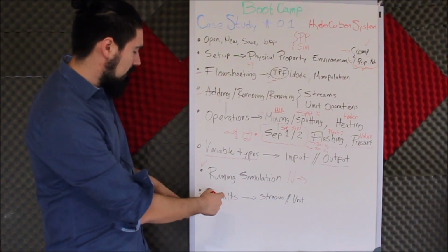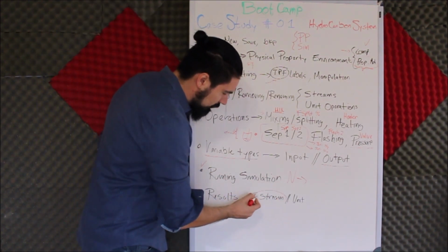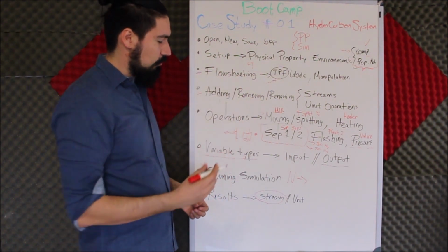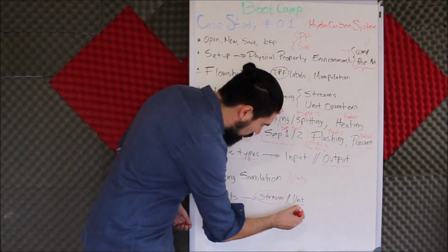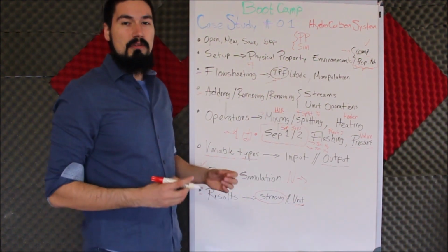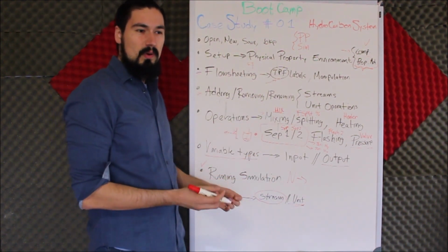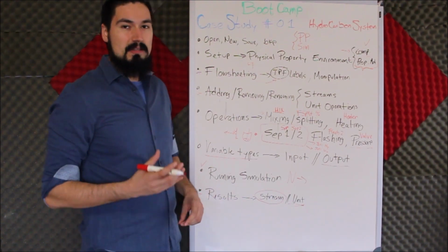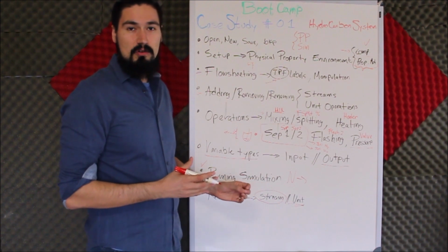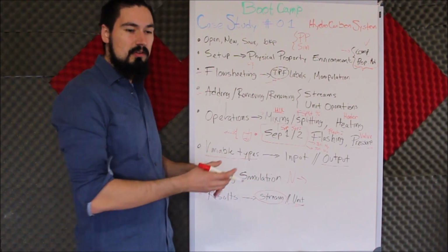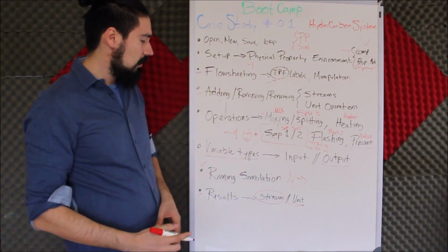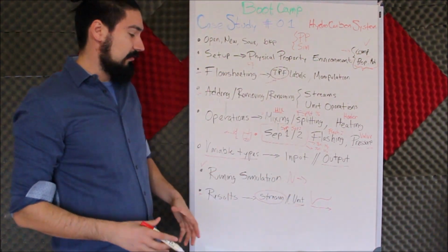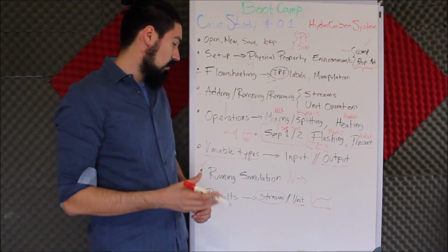And also, most likely what we want are stream results, the product results, what's happening, are we achieving our purity or not, and then we go and verify our unit results. For instance, if we're talking about the reactor, what is the heat duty, what is the conversion, the residence time, and so on. If we're talking about a distillation unit, you will want to see how much heat duty is required in the condenser, the reboiler, maybe the profiles. You want to see the pressure profile, temperature profile, composition profile, and so on.